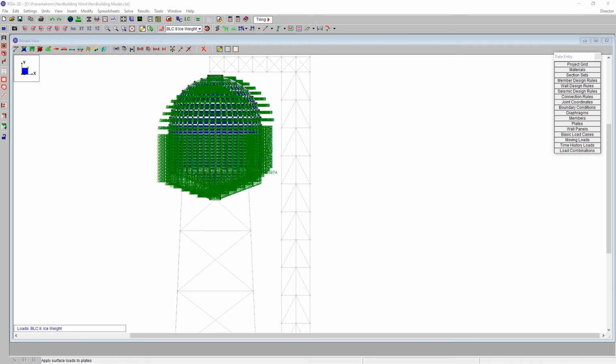And then for the ice wind in this case, we figured out that this would just be the same wind load in terms of magnitude. And so coming back to that one, that magnitude was 20.2. And if I take that one and divide it out, what we're going to find out is we have about a 2.4 psf wind load that we need to apply to the tank.